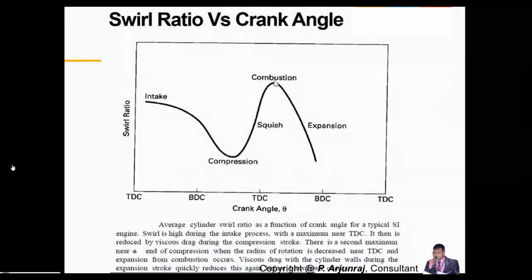Okay, I told you this fill ratio is also a function of the engine speed, and it also depends on the average piston speed and the angular speed of the engine. In the case of combustion, once the combustion starts, the pressure shoots up. When the pressure shoots up, it is again a function of the speed ratio. Your speed ratio is going to be higher, and you're going to get expansion. With expansion you also have drag, similar to the drag you get here. That's the reason you get a lesser speed ratio here.